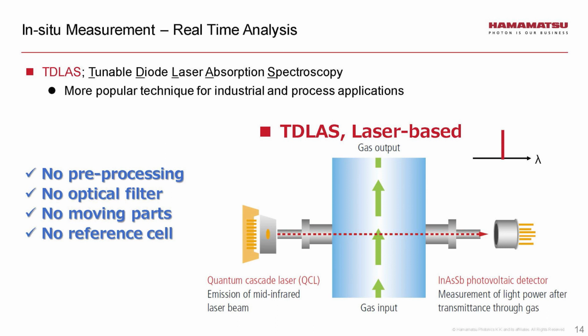This may not be the measurement to make, but you can simply have the laser shooting across a gas stream with a detector on the other end, and there is your measurement. Because you're getting that wavelength right away, and all you need is the detector to apply the Beer-Lambert law. So it opens up a whole lot of possibilities for quicker, more agile systems.